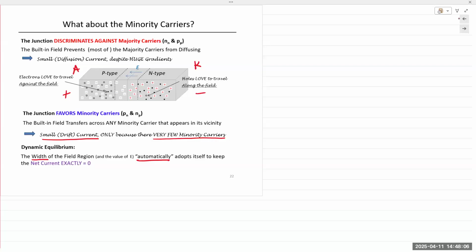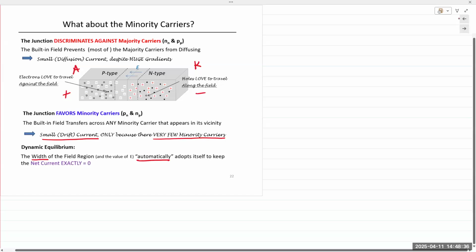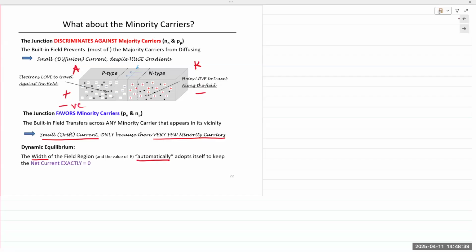Like after 0.5 volts, you'll see a slight increase in the current, meaning the electrons and the holes are acquiring sufficient energy to actually move through the junction. And after it crosses the junction, exponential increase in the current. Okay. And so application of positive charge at the anode and negative at the cathode allows the holes and the electrons to cross the junction. And we say that this is forward operation, forward bias. On the other hand, if you apply negative and positive, what's going to happen?